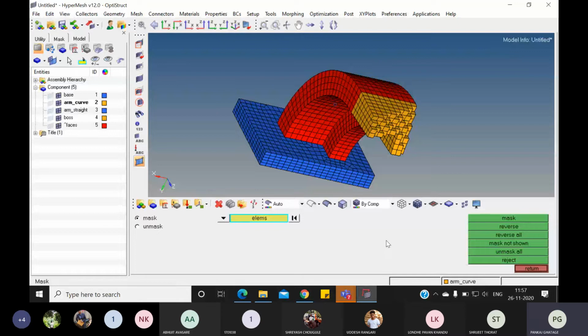That also you can do, but if you go with this kind of meshing, then the pattern will remain smooth and that mesh will be generated properly. You can check out by doing meshing with this method, and you can do the other method also. Okay, whatever you have learned, check out how the mesh will be generated. Yes, hex mesh, for hex mesh we are doing that one. We can use the random penta hexa, then a mixed mesh will be generated over there. But with hex mesh you will get a proper result for such kind of geometries.